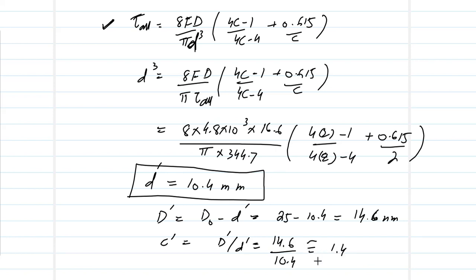It's a very small spring index for these kinds of springs, and as I told you, in the exam the spring index should be in the range. If it is not in the range, you can just write a comment on how we can increase it. You do not have to recalculate in your exam, but you can comment on how to increase it. In a simple way, in this case, if we increase the outer diameter, probably the spring index will increase. So this is one argument you can write in your exams.